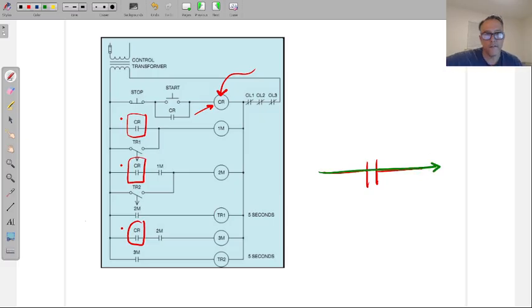It can go on to the next thing down the line. While that is in the open position, voltage is not going through. So the first thing that has to get power here is that relay coil, and then all of these will close at the same time, and now these things get power forward. But you'll notice I run into another open situation here.